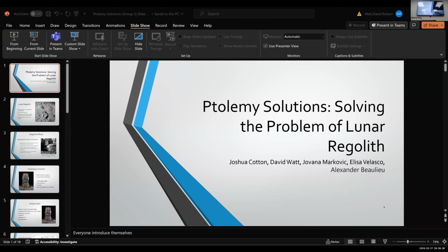So consider, although you did mention you're planning on this being down at a temperature of like 5 Kelvin, whatever gas you're pressurizing with on Earth, PV = nRT, you're not going to have a 98 kilopascal difference at 1 atmosphere in an Earth environment. It could potentially be at Earth pressure and then cool and reduce the pressure to the 2000 pascals that you're looking at targeting.